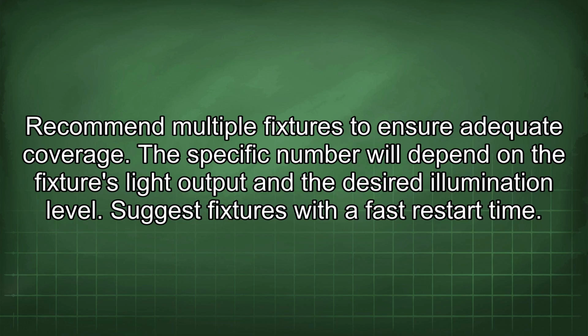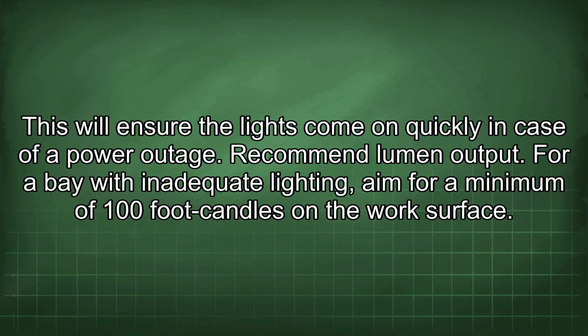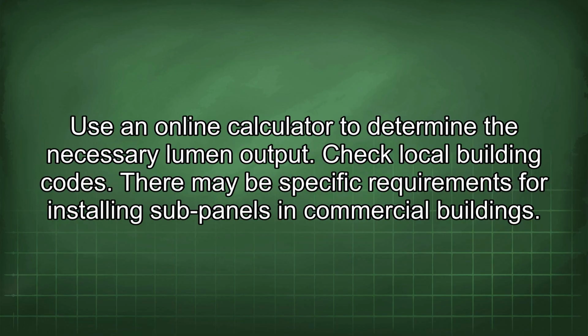Suggest fixtures with a fast restart time. This will ensure the lights come on quickly in case of a power outage. Recommend lumen output. For a bay with inadequate lighting, aim for a minimum of 100-foot candles on the work surface. Use an online calculator to determine the necessary lumen output.